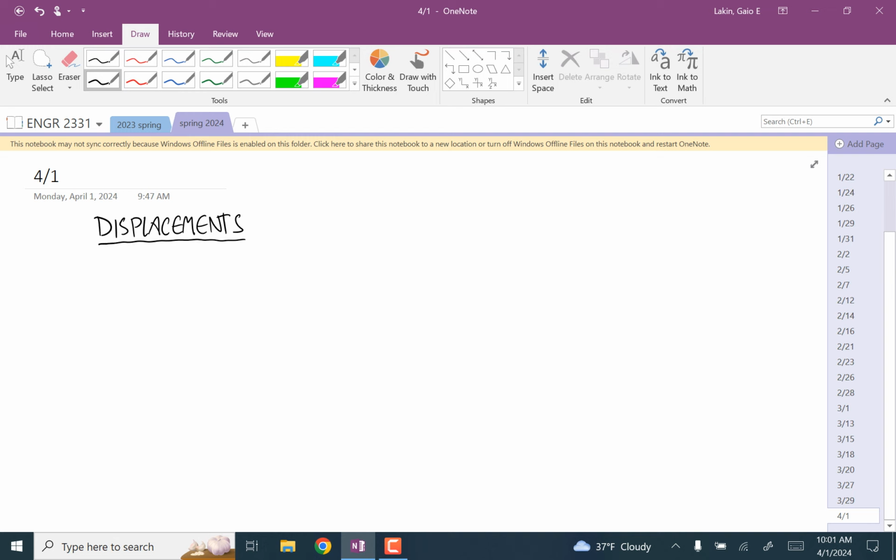And you can think of this as the total displacement, the difference in the location before the loads are applied to after the loads are applied, is equal to the displacement due to tension and compression, plus the displacement due to thermal changes, temperature changes, plus the displacement due to torque, plus the displacement due to the bending moment.